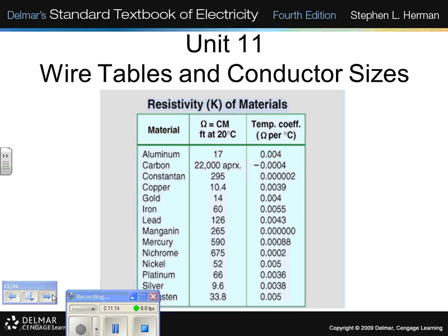Now, that doesn't make any sense, because between 20 degrees and 30 degrees centigrade, you have a positive correction factor, remember? But at 30 degrees and higher in temperature, you have a negative derating factor, right? So the derating factor starts at 30 degrees. Guess what number you come up with if you plug in 30 degrees centigrade instead of 20? 10.8.